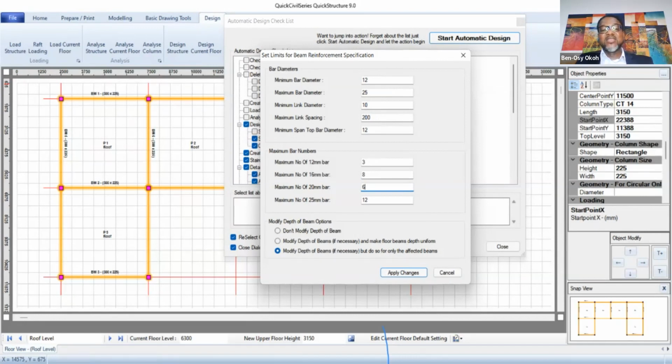Then the same thing applies also when it is moving from Y20 to Y25. So instead of when you finish your work, you begin to go through them one after another. Oh, I think there will be a cluster here. Let me change. You begin to recalculate and go through your books again to know what is the number of bars I'm going to provide in this particular area using Y20 against the Y16 you used initially for your design. So this is just what this does.